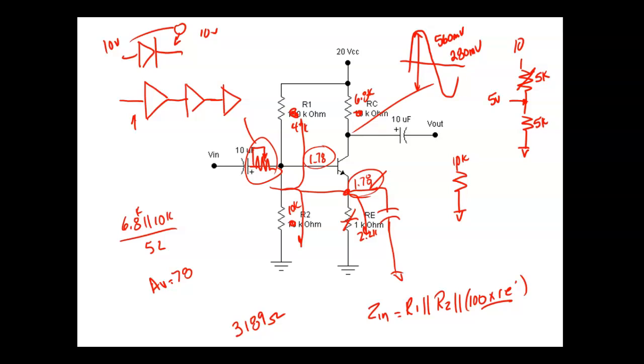So basically on most of these things, when you make these bias measurements, most of the time it's going to give you two components. And what we do is we try to eliminate one of them, right? You understand? Yes or no? So y'all know why we got 1.78 volts right there. Because that diode, that PN junction, is not acting like a PN junction because it's not forward biased, it's acting like a resistor.